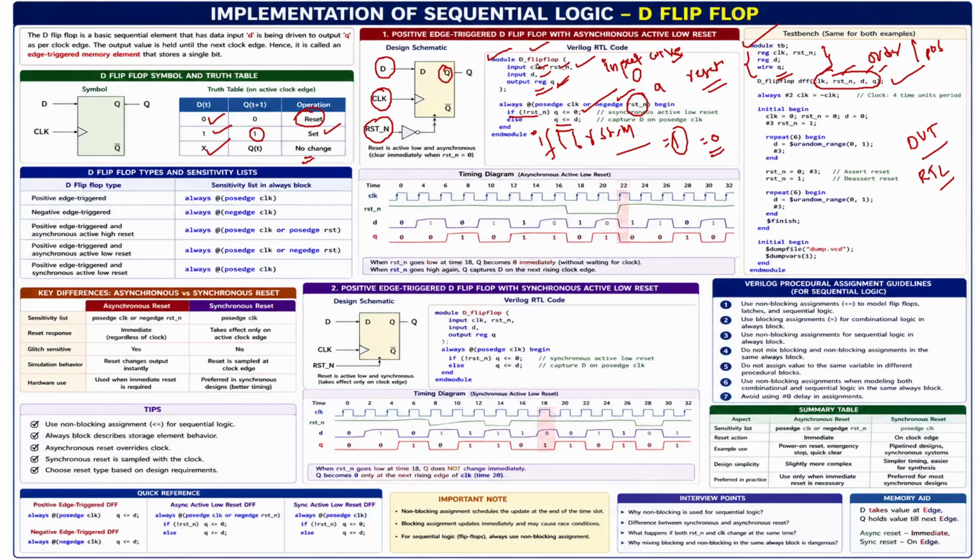In the test bench we can reverse this, because I told you in the ports representation, wire is used on the input side. Inside the initial begin block you can use reg only on the input side, and in the external world you can use either wire or net type, sorry, net type or reg type, in most cases. Most of the time on the test bench side we are storing values, because the output is not storing any value; we are capturing the values only. That's why we use wire only at the output side. And on the test bench side you are passing the stimulus, which means you need to store the values. That is the purpose we are using reg.